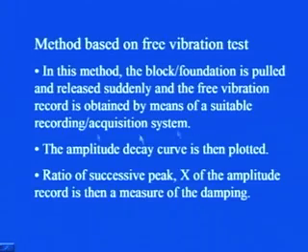Once this block or foundation has been displaced, it will vibrate under the inherent forces, so the amplitude of the system will go on decreasing with time. That amplitude decay curve can be plotted because a suitable measure has been provided to record this amplitude.